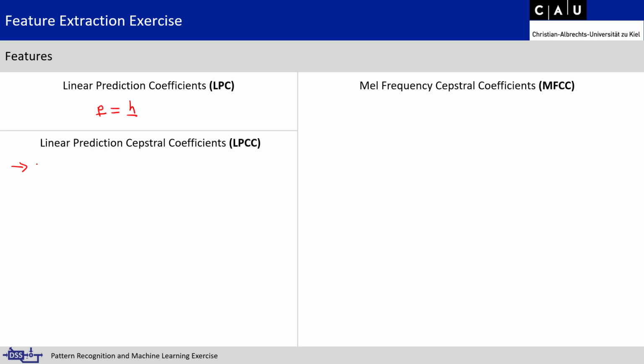These are actually the cepstrum of the inverse of the prediction error filter. So what does this mean when we say that the LPCC features, they're called c_i? And then let's get the cepstrum. So we have our inverse of the prediction error filter in the frequency domain. I'll use the DFT notation here with subband index mu. Then taking the cepstrum is we take the logarithm, and then we perform the IDFT.